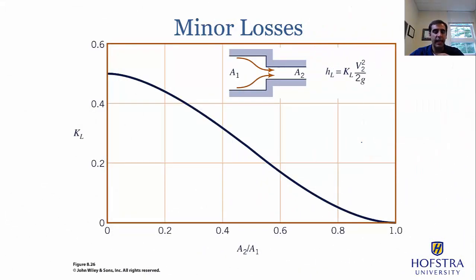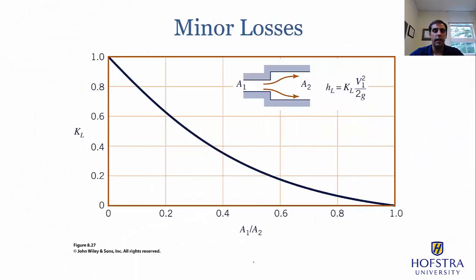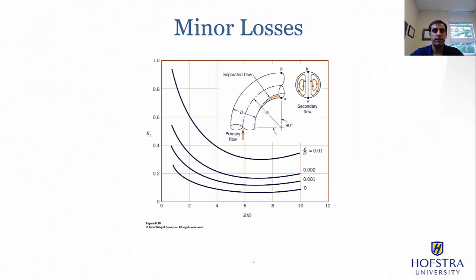And so you'd see tables like this that are calculated from other people's experiments, which allow you to get estimates on what your loss coefficient is dependent on the area ratios. Okay, so you'll find out what you have. You can measure what those ratios are and come up with an estimate of the loss coefficient, and you'll compare that to the experimental data that you collected, right? Well, again, in your exit, or if you have an expansion section, the area ratio is going to affect what that loss coefficient is.